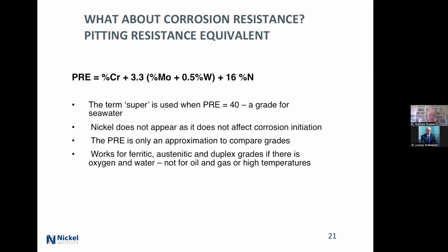And nickel isn't in that. So people who do an analysis and say, no, there's not enough nickel in there, the corrosion resistance is awful. Well, it's not true, because the nickel basically affects the arrangement of atoms. So it looks after the mechanical properties of the thing.